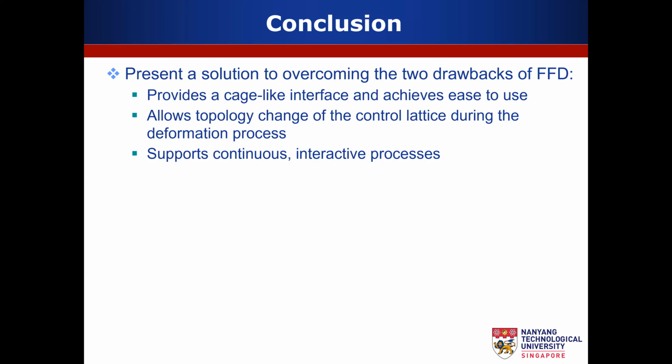So in conclusion, we present a solution to overcome the two drawbacks of FFD. It has several nice features. Firstly, it provides a cage-like interface for the user to perform freeform deformation, which avoids manipulating too many control points and is easy to use. Secondly, it allows topology change of the control lattice during the deformation process, which is not possible for most FFD methods or cage-based deformation as well. Thirdly, it supports continuous and interactive deformation processes.